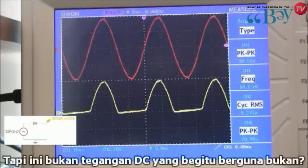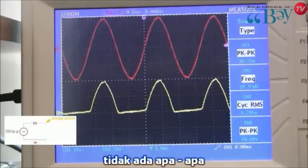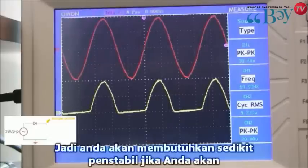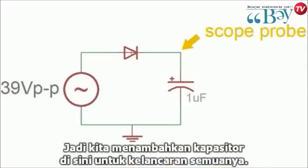But this isn't very useful DC, is it? Half the time you've got a weird hump-shaped voltage, and half the time you've got nothing. So you're going to need a little more stability than that if you're going to power anything useful. So, we add a capacitor here to smooth things out.